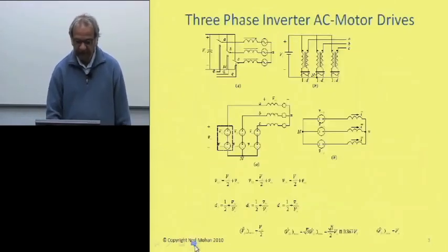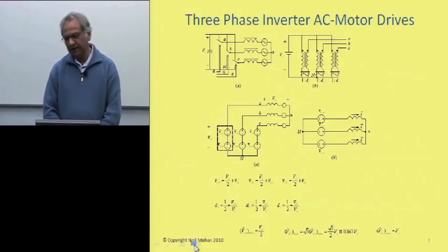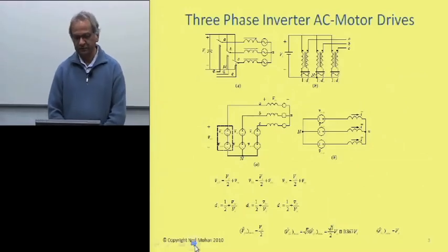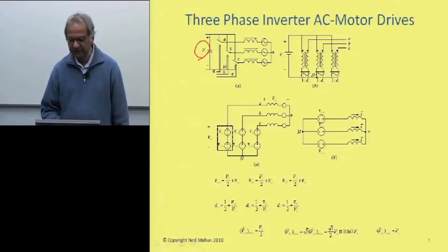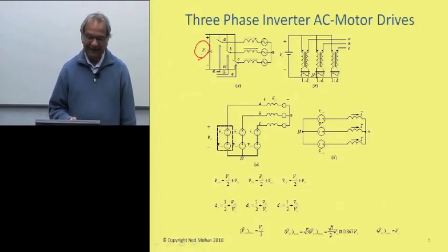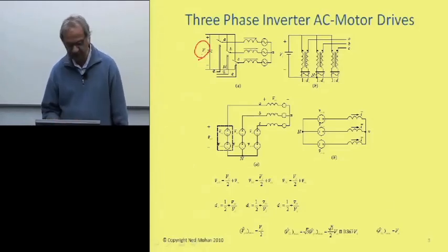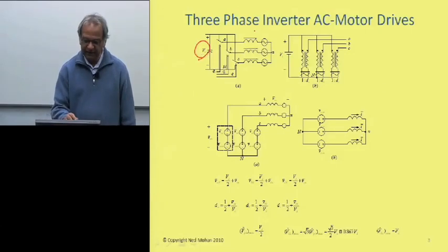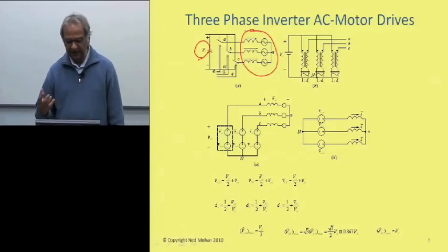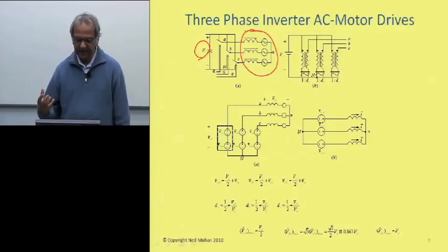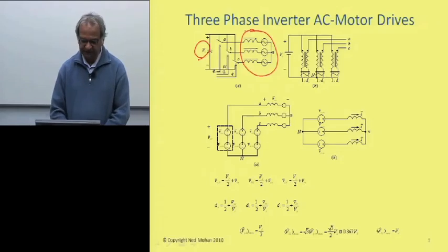Let's move on to three-phase. Quite often they are called inverters, but you can call them converters for AC motor drives. So once again, you have a DC bus voltage here, and you would like to synthesize some low frequency AC, usually sinusoidal, across this AC motor over here. An AC motor can be represented by some inductance, and at the back there's a back EMF, so to speak.